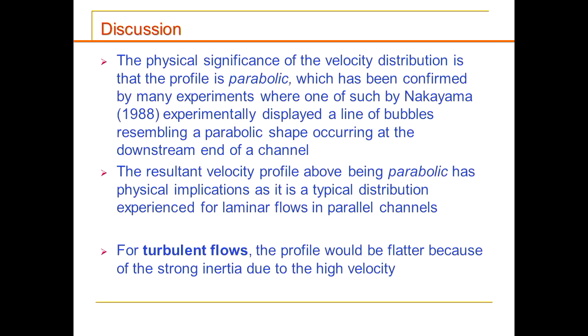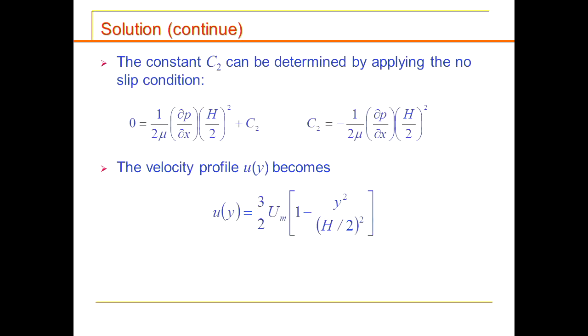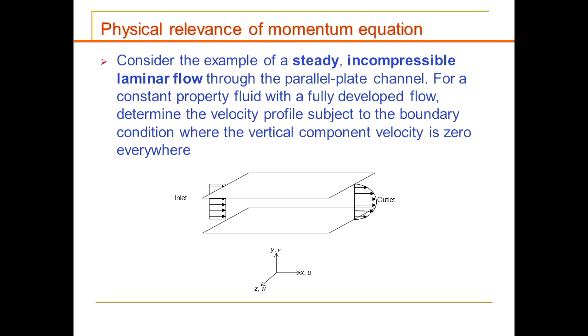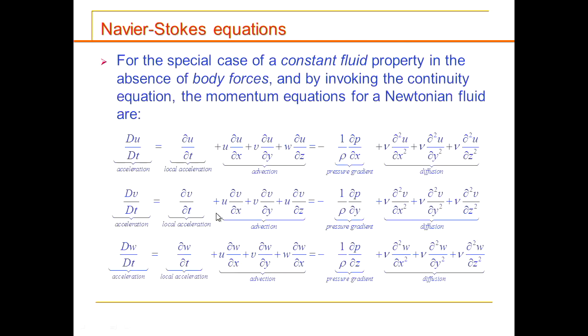If the flow is turbulent, however, it will behave very differently. As Guan already mentioned to you guys, you won't develop to this perfect parabolic profile. You will remain something similar to your inlet flow. We can actually explain the reason through the governing equations as well.